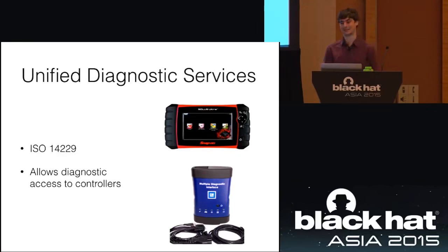Unified Diagnostic Services, it's this ISO standard 14229 if you want to Google it, and it defines a diagnostic system that is used by every automotive manufacturer. The reason is because when you take your car to a mechanic, they're going to use a tool like that thing up top, the Snap-on scan tool, to take a look at it. Now, they don't just get OBD. They get another set of messages that's manufacturer-specific, but that manufacturer has to provide them a database.